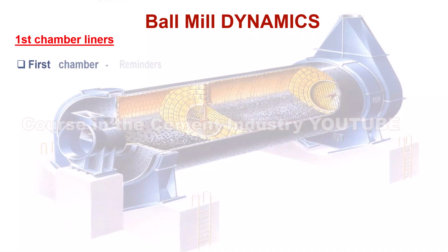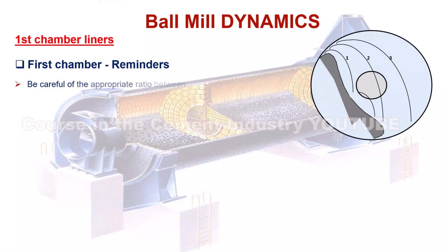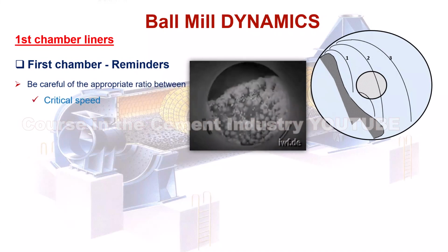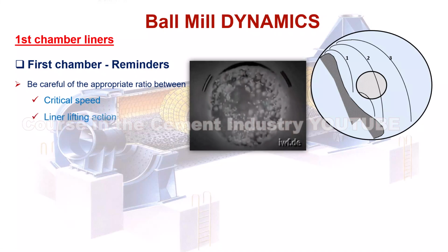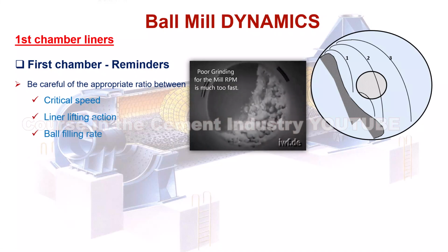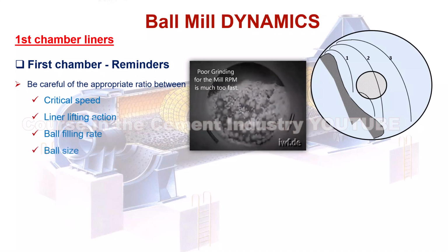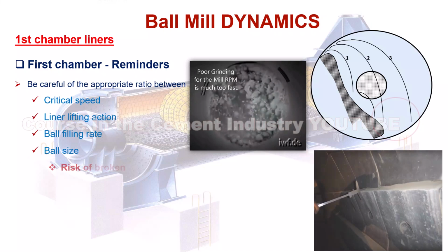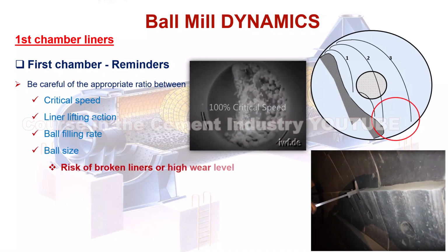First chamber reminders. A. Be careful of the appropriate ratio between 1. Critical speed. 2. Liner lifting action. 3. Ball filling rate. 4. Ball size. Note: risk of broken liners or high wear level.